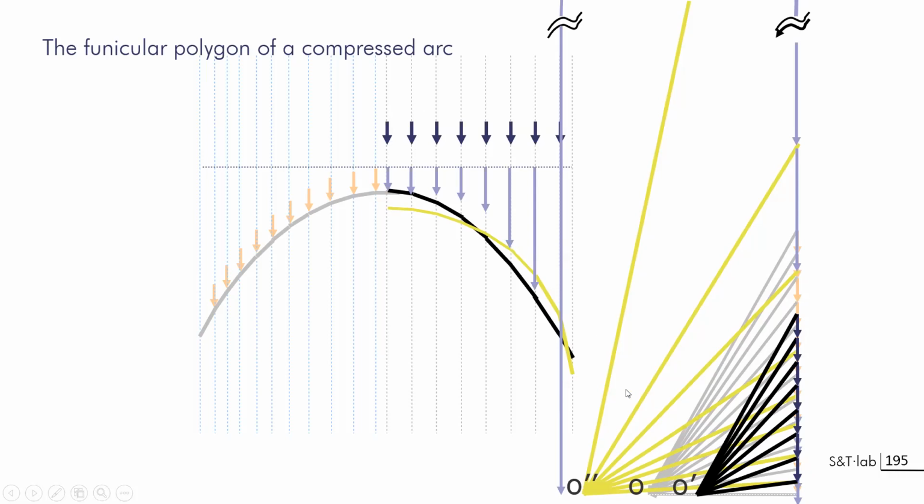So you know the orientation of each of these vectors by drawing parallels to each of the line segments of this line. And so it shows you that this figure is very hard to create, and you have a force that is nearly infinite on the side. And in any case, you will need more forces on the side to create such a system. So it explains why this is not widely used in cathedrals, for instance, in the past, and that you will have devices such as flying buttresses on both sides to create the system.